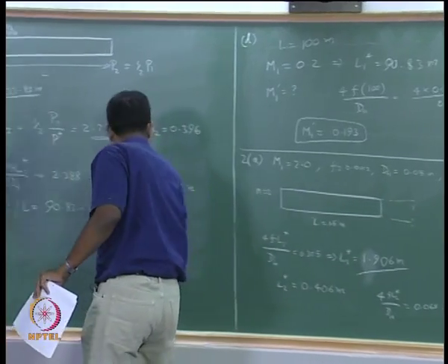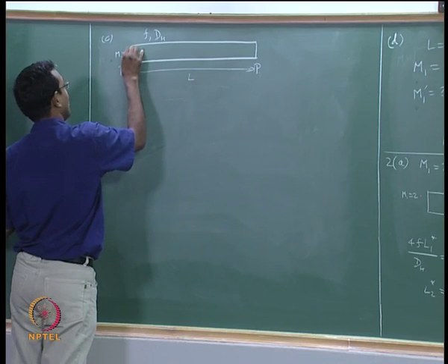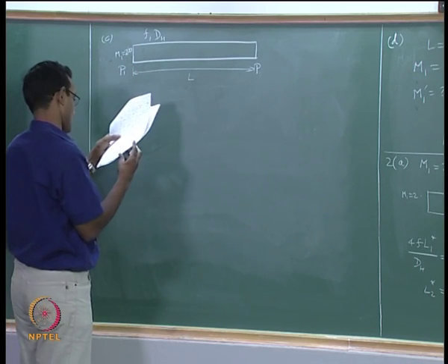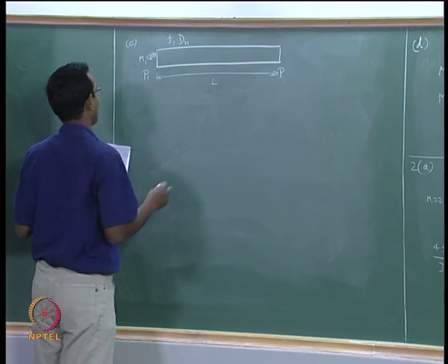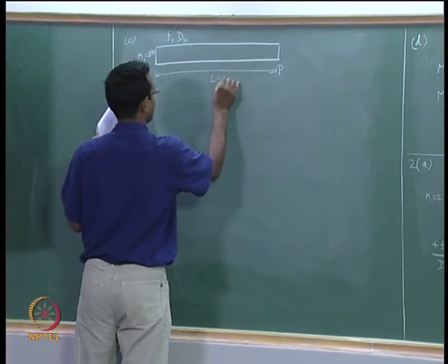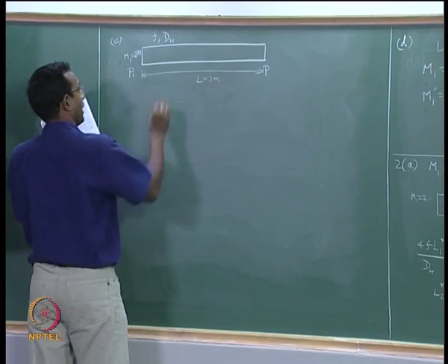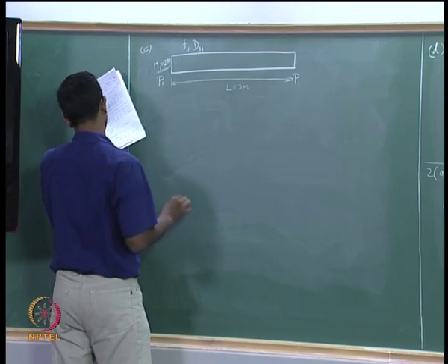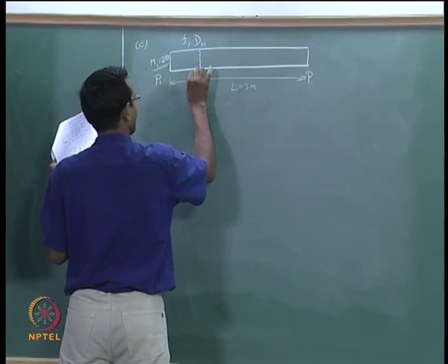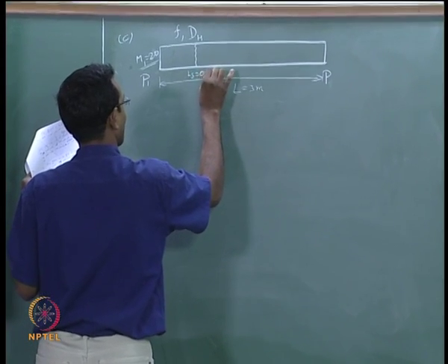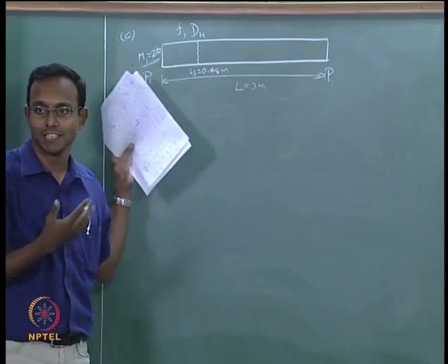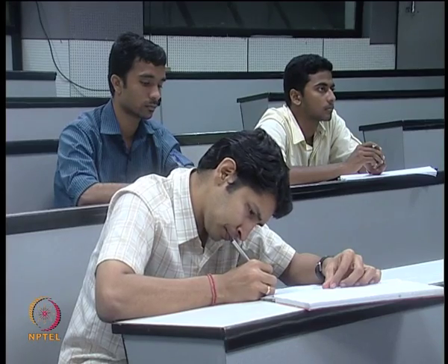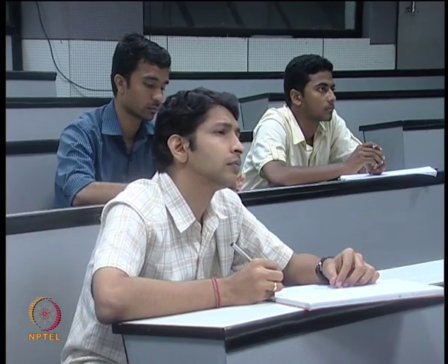So, now this becomes here in 2C, I am starting with M1 equal to 2.0, same f, same D_H. Now, I am telling I have that exact situation like in problem B, I am having length equal to 3 meters, okay, and we started with M1 equal to 2.0. So, we know my shock location is LS equal to 0.45 meters. Maybe I am right, maybe it has to be 0.442 something, I will just assume it is 0.45 right now. Okay, I did not go through one more iteration to make it any more accurate. So, we will keep it as 0.45 meters.